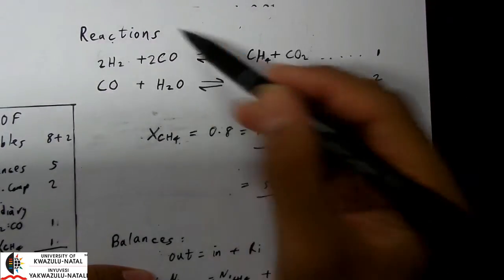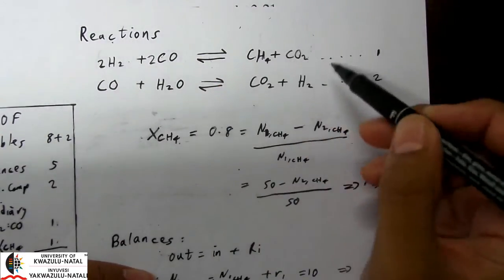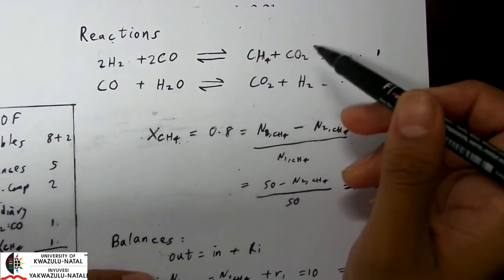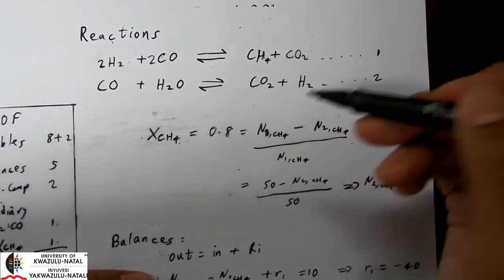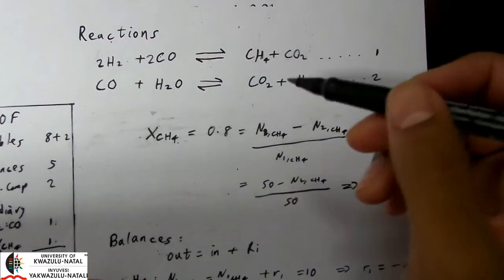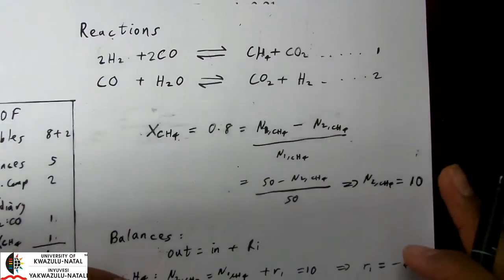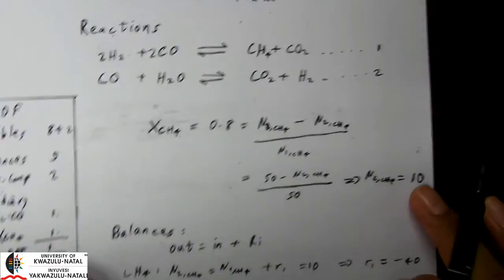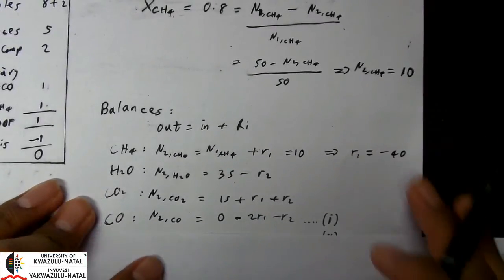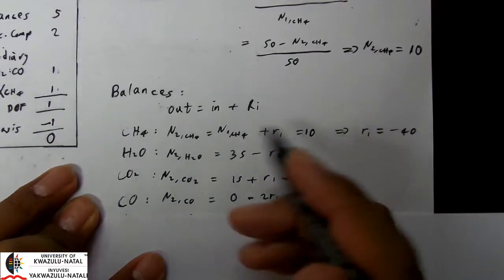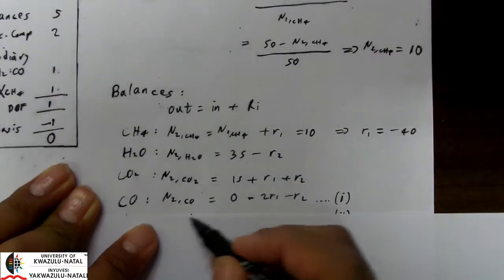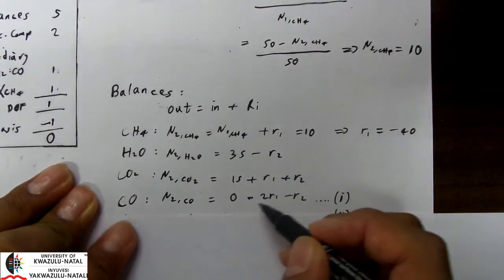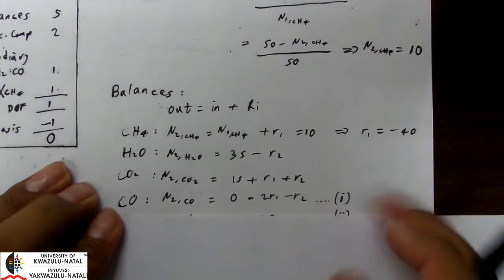So I'm working with the reduced reactions. They are not necessarily making any sense. However, they are valid and consistent from a material balance point of view, and that is what's important. That's what's relevant to us. Okay, so just be very rigorous about this. Write out the expression. We have our output is equal to input, and we have CO being used up.